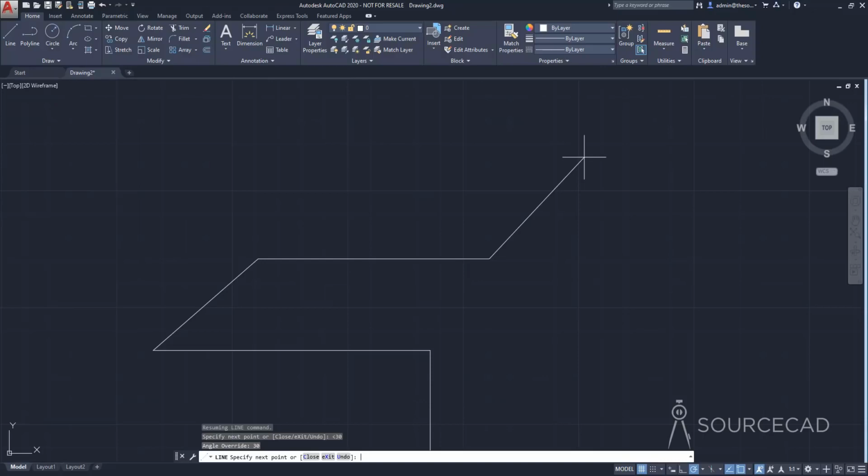not as distance. So if you move your cursor now, you're going to see angle override here, which is now set to 30 units. So if you now move your cursor, the length will change here, but not the angle. So all you need to do is now type in the length. So maybe I'll type 50, enter, and here it is. So now the length of this line is 50, and it is inclined to an angle of 30 degrees with respect to positive side of x-axis.